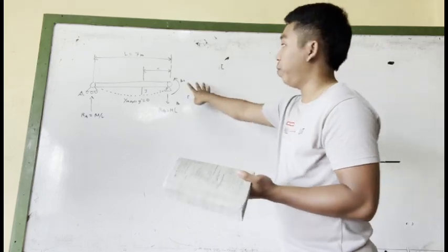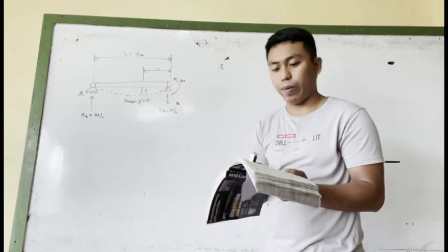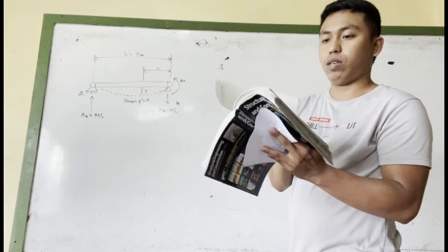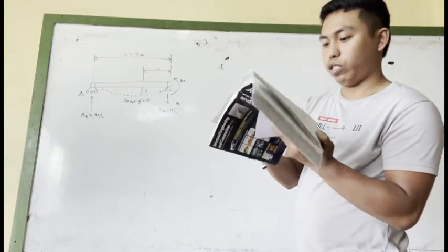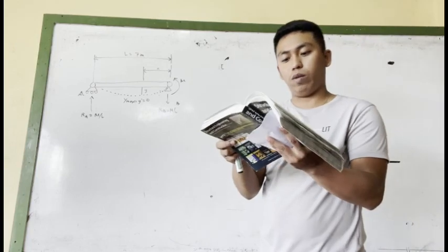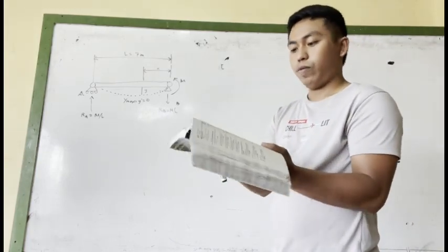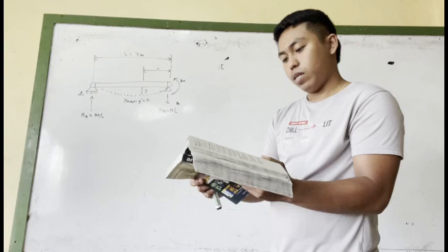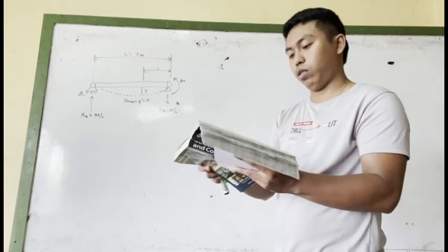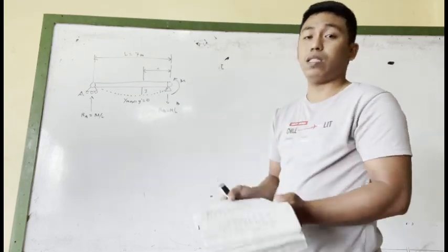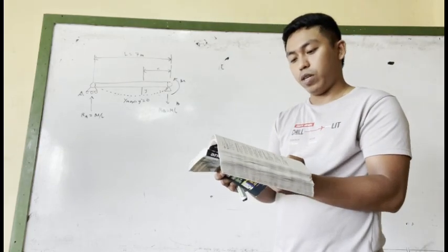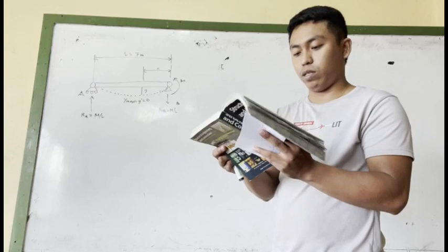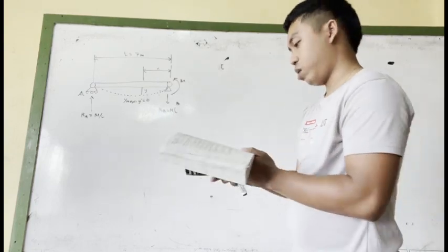So this problem consisted of two requirements, which are the maximum deflection, which is located at this distance from the applied load, and calculation of the value of maximum deflection, which uses the modulus of elasticity of 200,000 Newton per millimeter squared and the inertia of 60 times 10 to the power of 6 millimeter to the power of 4.